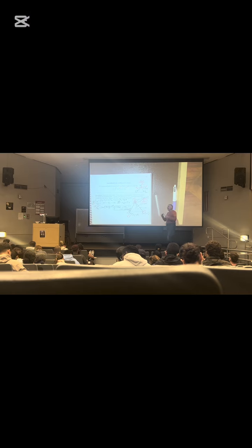0.3076 FPC I minus 0.2301 FPC J and minus 0.9231 FPC K. There is my FPC in terms of IJK. The goal in any 3D problem, get me forces in IJK format. Did I accomplish that goal here? Yep. Now I got to repeat it for PB and PA.